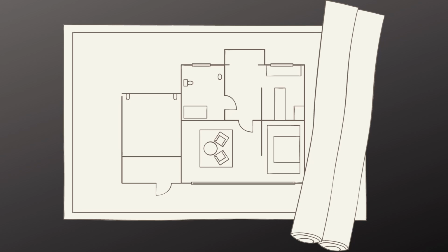In this step, the architect gives you the basic idea about the design, style, material, and many more details. After being approved by the client, the architect generates the final plans, and that's step number 3. You have to review the final designs very carefully because after your approval, the architect starts to work on the permit drawings. Also, he sends drawings to other agencies for their designs, like engineered floor or truss roof companies.